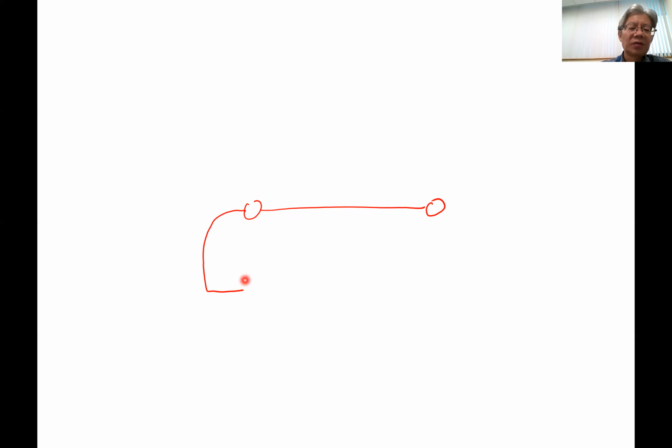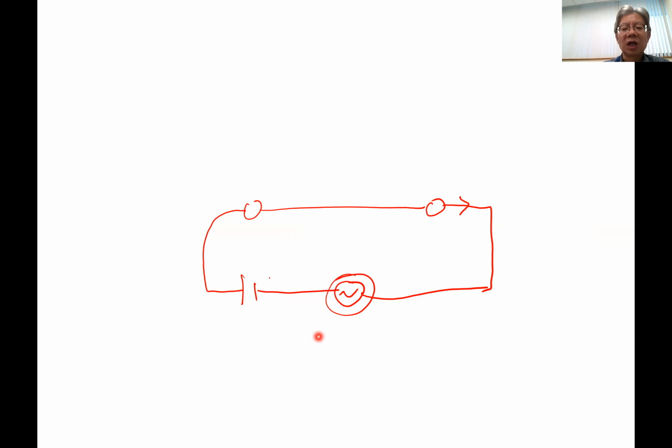You know why? Because for example, if this is a power supply, and you connect your signal here, your signal may be a DC or AC signal, right? In this case, why can you not amplify the signal? Because you get the output from here. Your output and input are on the same line, right? Current flowing in the closed loop should be the same at any point of this closed loop, due to this charge continuity requirement. So if your signal has a certain amplitude, your output has exactly the same amplitude. This is the reason why you cannot amplify.